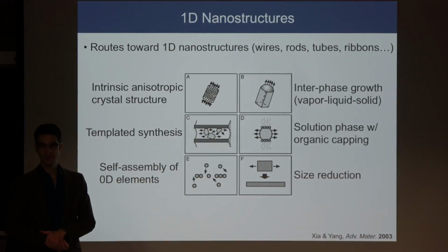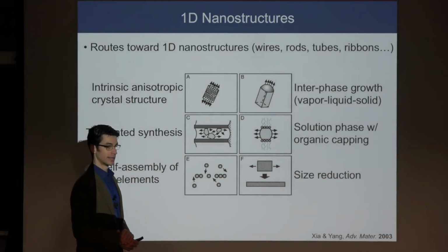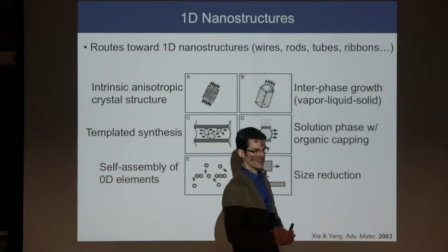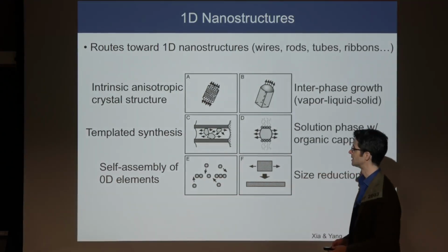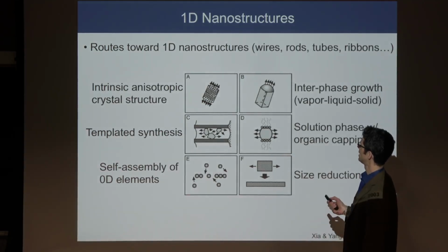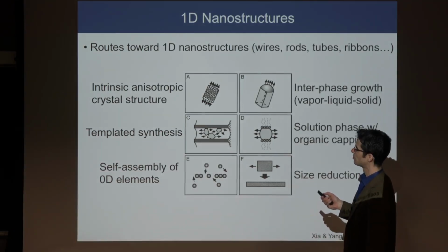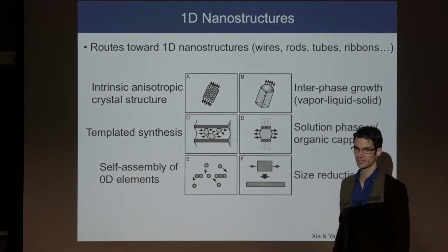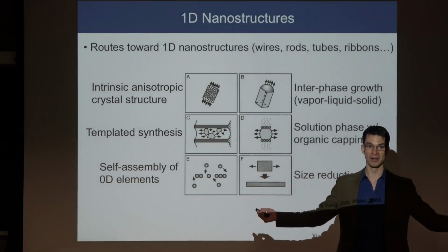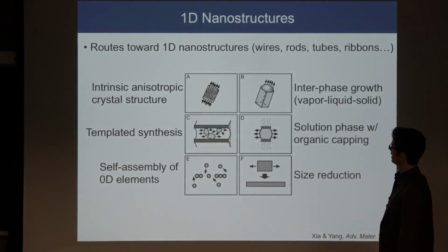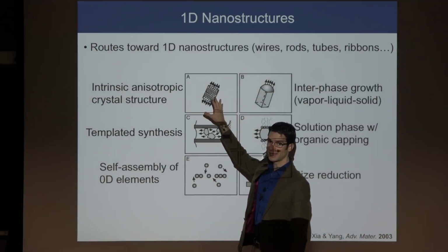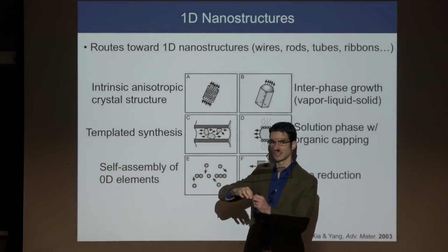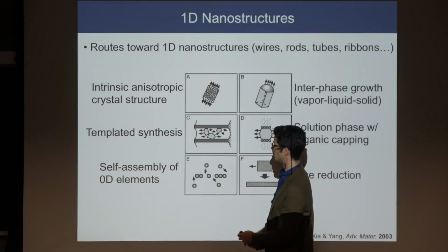Okay, so how about one particular class of nanostructure, and nanowires are quite important in the research lab, but also increasingly technologically. And these are in some referred to as one-dimensional nanostructures because they're long compared to their cross-sectional dimensions. And you can have many different ways of creating one-dimensional nanostructures. You can have, for example, structures whose building blocks have an anisotropic crystalline morphology where it selectively grows along one axis as opposed to the other two.